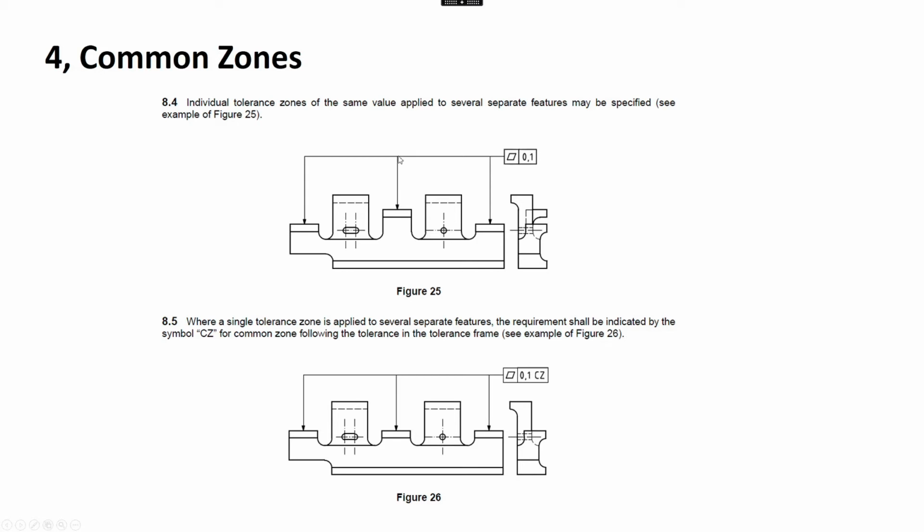This top example, I don't particularly like this top example. I think if I was detailing this top example, I would put a box dimension from this pad to this pad at this location here, whatever that's going to be. Put a box dimension on that, and then change this to a profile tolerance. I think that's the way I would show this, because I think it makes more sense and people will understand that better than this example.